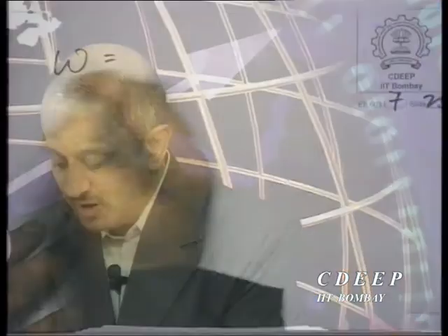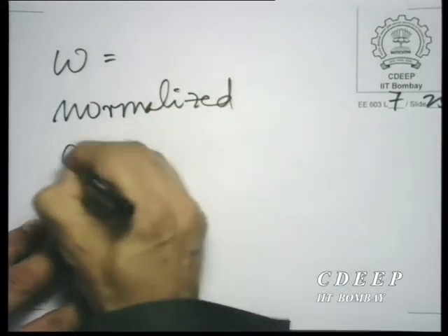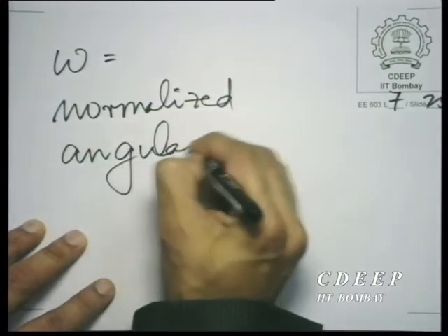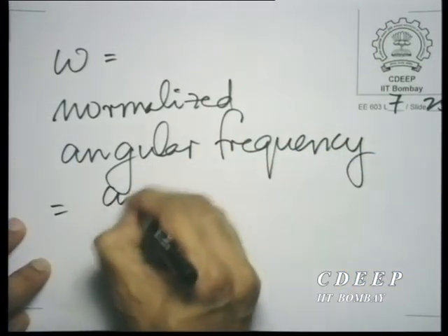So, whenever we are dealing with a discrete system, we will assume that we have chosen the unit so that 1 unit is equal to the sampling frequency, and therefore, the sampling period is 1, and thereby we shall use small omega to denote what is called the normalized angular frequency, or the angular frequency in these units.